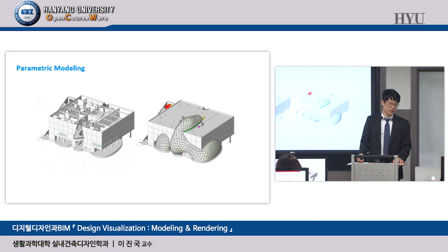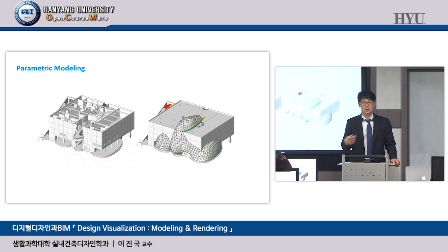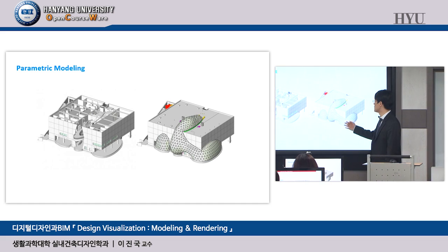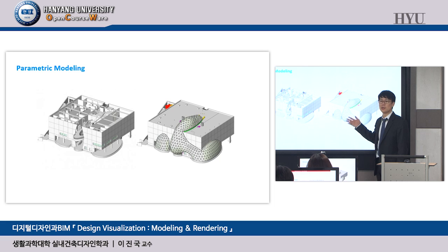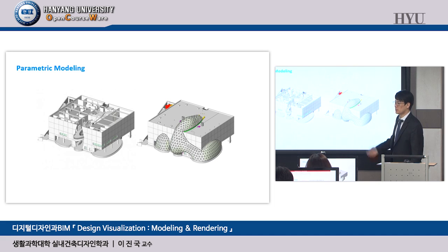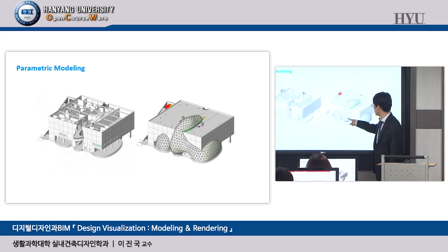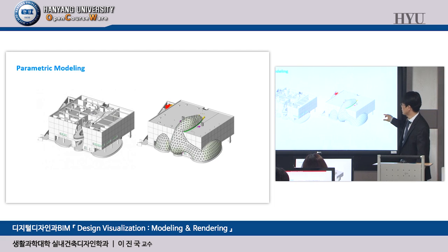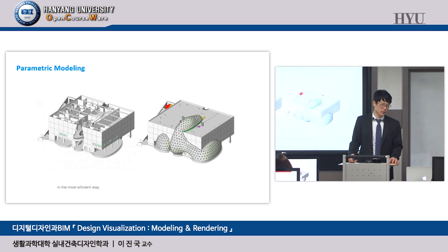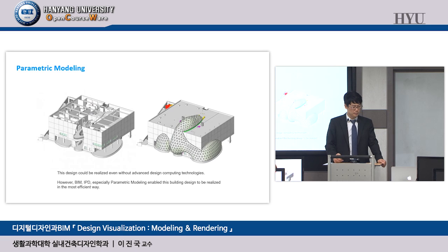That's the difference between BIM-based design approach and geometry-oriented design approach. If this is just a Rhino model, 3D Max file, AutoCAD file, no one guarantees any single line here is going to be realized or not. But this is a BIM model, a parametric modeling based model, which means the number of pieces defined here is supposed to be realized. In other words, the picture and this screenshot are going to be exactly the same. Okay.